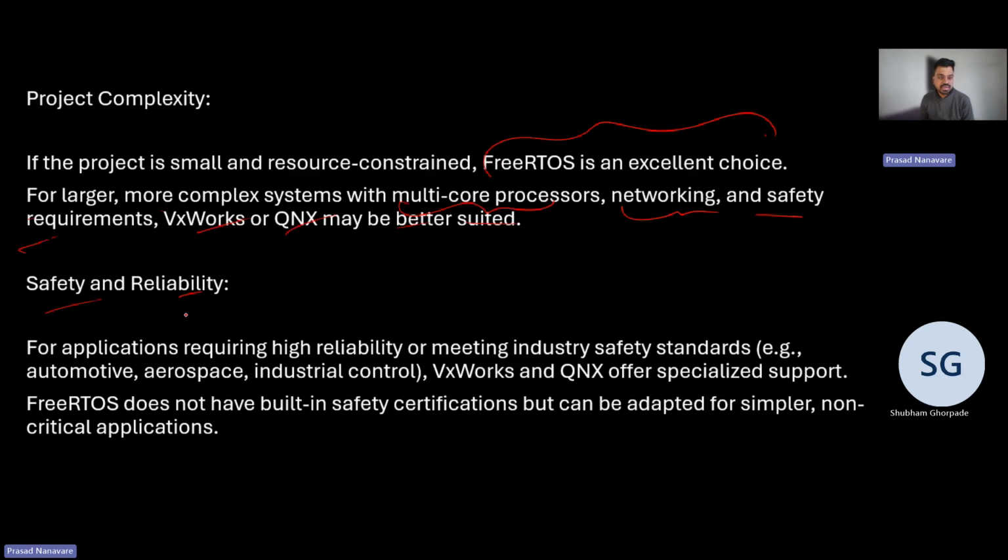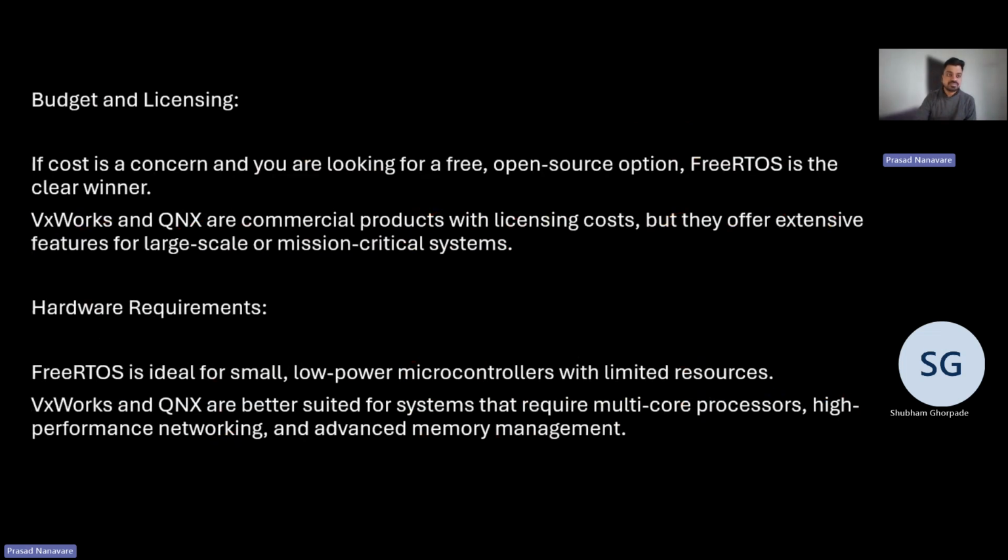Then safety and reliability: for applications requiring high reliability or meeting industry safety standards, for example automotive, aerospace, industrial control, VxWorks and QNX offer specialized support. FreeRTOS does not have built-in safety certifications but can be adapted for simpler non-critical applications.